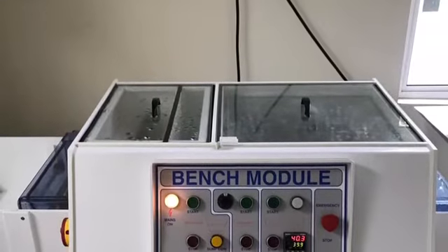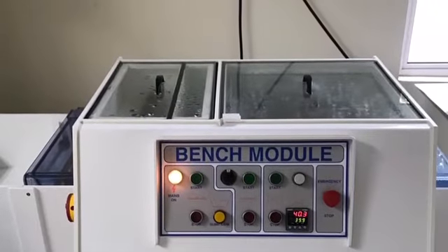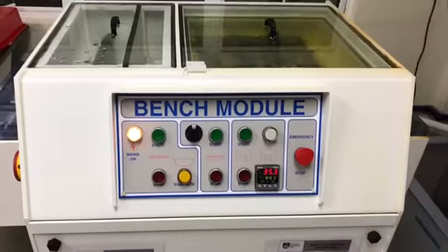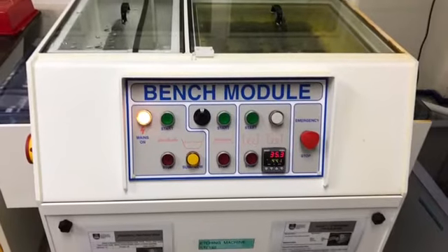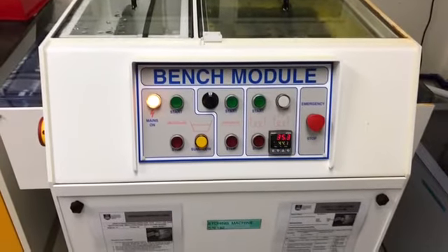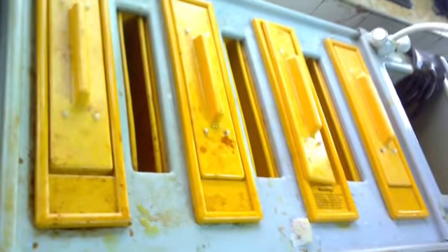The next step in the fabrication room is the etching process. In this step, the machine will wash ferric chloride over the board, eating away any exposed copper. Then, we need to immerse the etched circuit board in photoresist stripper.